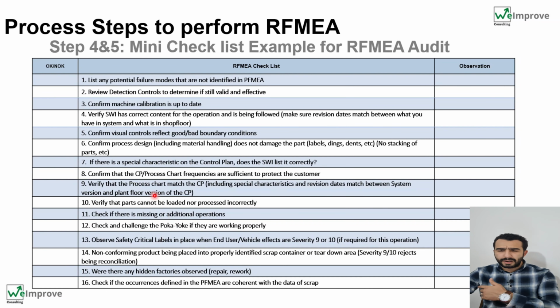So you have a lot of questions that can help you, or help your team, to check and do it in the correct way. So whenever you find that something is not good or not correct, we have to put the observation here. Every observation becomes a new potential failure mode which should be included in the PFMEA.